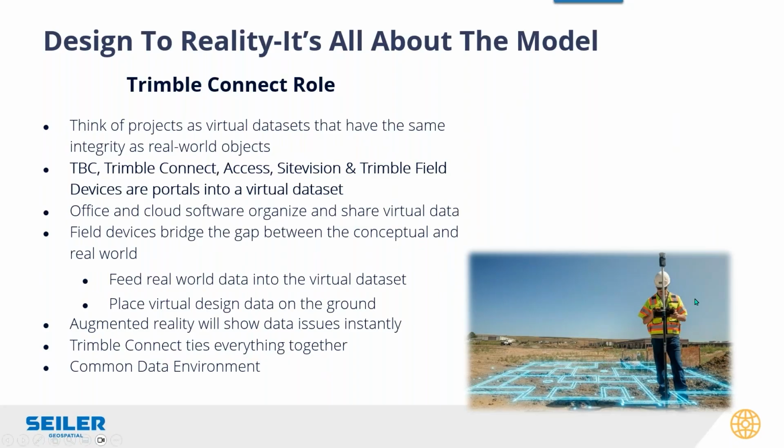You can see over here it looks like a construction layout. Here's the virtual model, and they're using our survey tools to lay it out on the ground. The quicker thing to do would be to blow this plan up life size, roll it out on site and go stick pins through it, but that's obviously not feasible. So we're using virtual models in our survey devices.